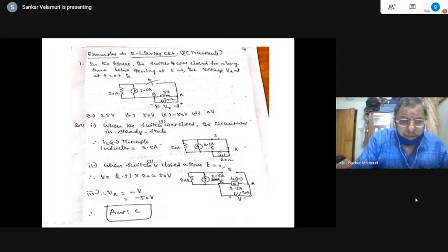So V will be at higher potential compared to A. But Vx is required to be obtained in the opposite direction, minus and plus. So therefore that is obtained as minus V. Our notation is obtained like this, but the actual direction required by the question is minus and plus. So the value of V that is computed should be reversed. According to the question and the notation given, what is required is that A should be at higher potential, so this should be minus V. So minus 50 volts is the answer.